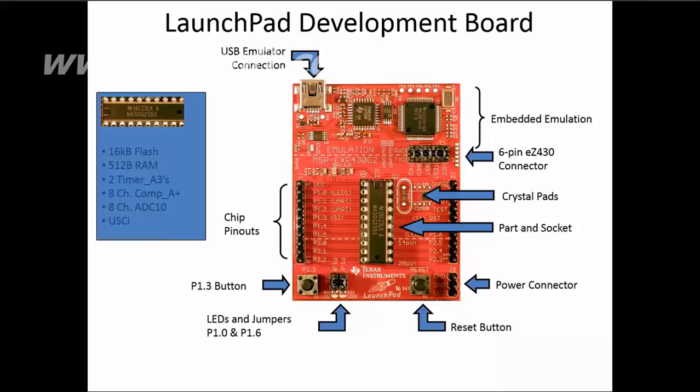A0 minus, A0 plus, and so on up to A4 plus or minus, are the inputs to the analog to digital converter. It has four different channels, each of which has negative and positive inputs. Vref is the reference voltage for the converter.